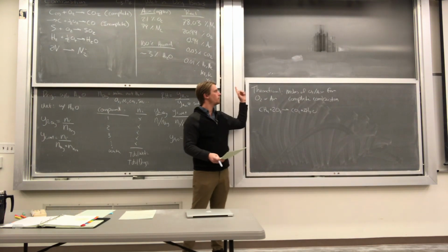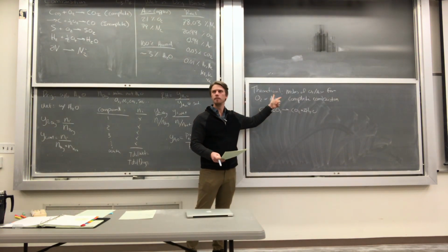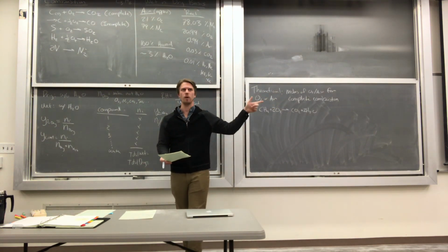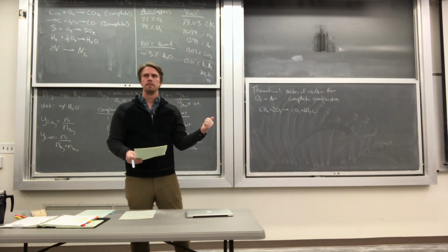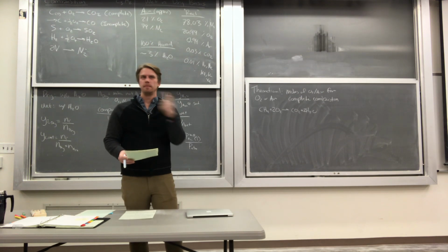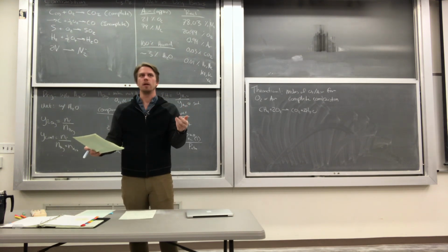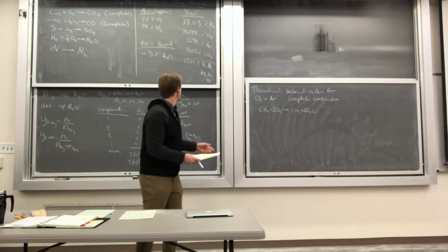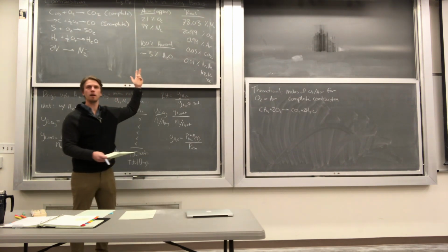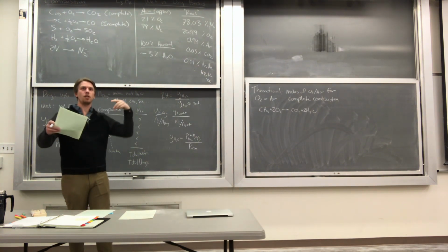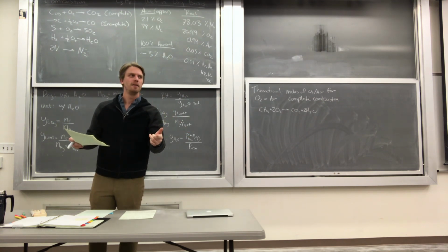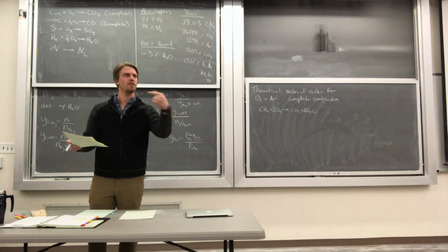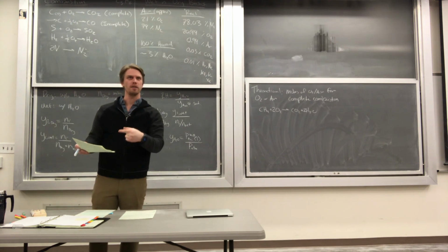Now, what would my theoretical air be? How many moles of air do I need for complete combustion? Divided by 0.21. Yeah, so it would be 2 divided by 0.21, right? Because that's the ratio of oxygen in our air. Now, if I had humid air, would I need more air or less air? More, because some of that is occupied by the water itself.